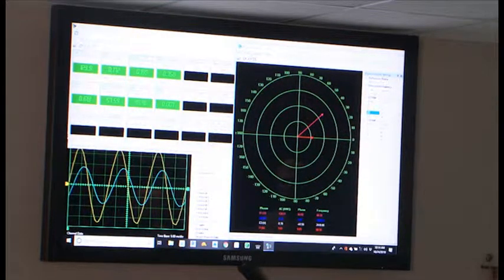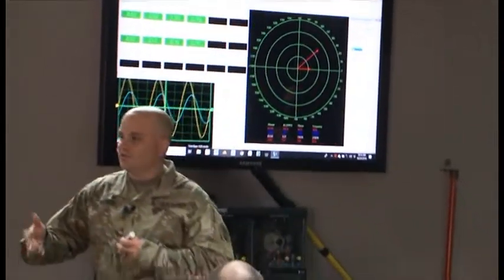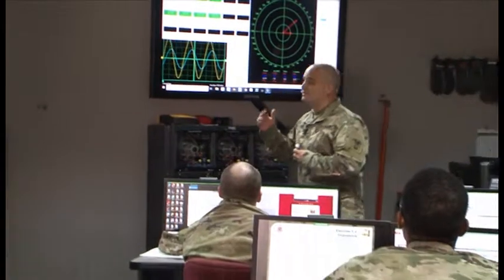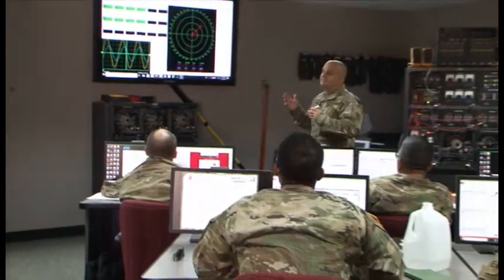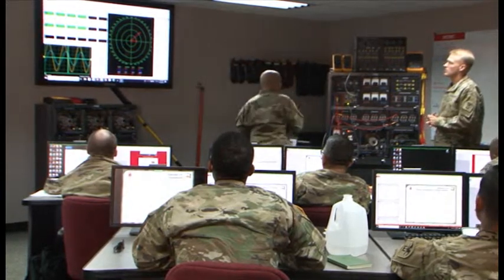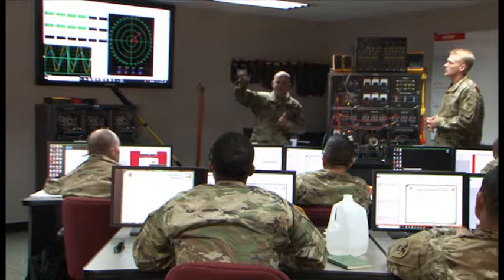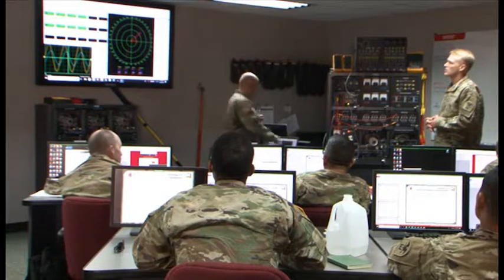What about the angular relationships going on right now? So here's kind of a difference too. On this phasor diagram, in a parallel circuit, what is consistent across all branches? The voltage. So we use voltage as the reference in the parallel circuit. Now again, you don't have to as far as how you're analyzing. It just depends on what you're trying to do, right? Some of the trickier word questions, you've seen them before, will ask which one you're using as the reference, but that same relationship should exist.